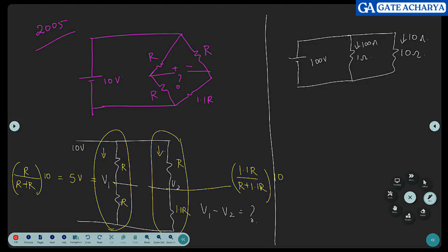I just want you to understand that when you talk about this branch, this has nothing to do with it. Because the meaning of a voltage source is that it is capable of supplying any amount of current across all the branches to maintain the voltage. To find out this current, we don't talk about that current. This current through this branch will only depend on this resistance. Something very basic, you all know. You can just spend some time.